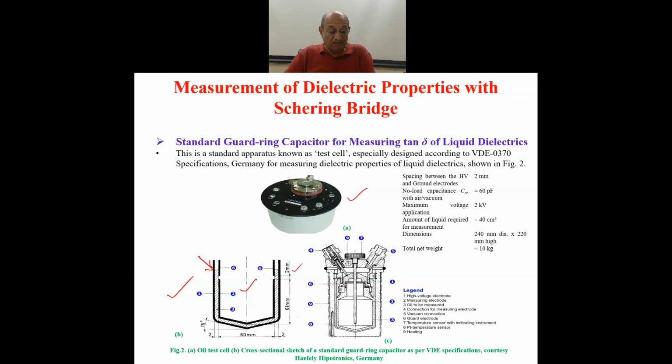In this form, when the capacitance is formed, it is nearly a uniform field capacitor. It is weakly non-uniform actually. The eta, if you calculate for this configuration of the two electrodes between which the capacitance is formed, it may not come out to be 1, but very close to 1, that is a weakly non-uniform field.